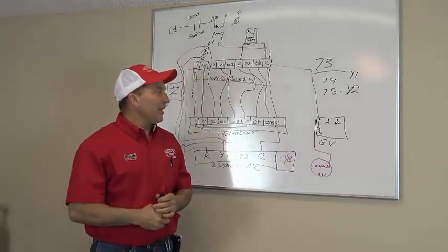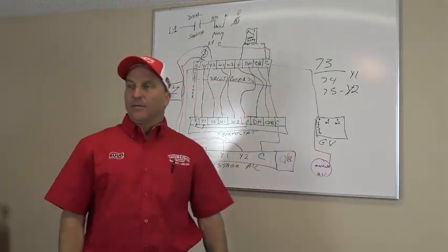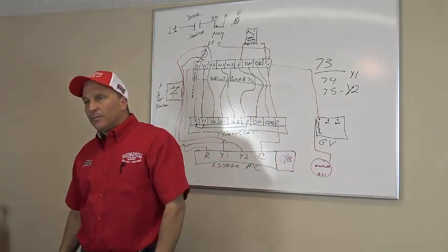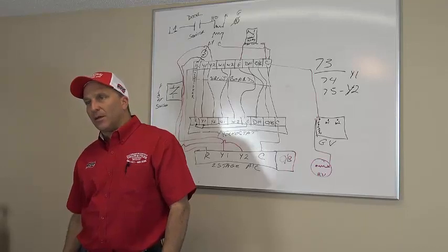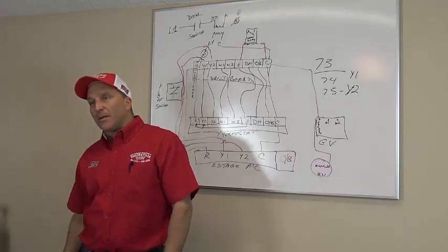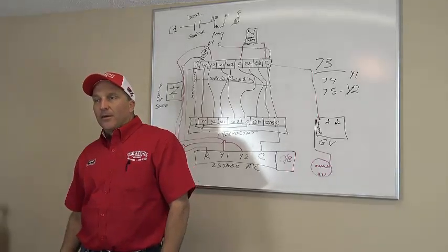Alright? Now, how else will Y2 kick in? Will Y2 kick in if I just go bury the thermostat down? Yeah, it will. But will it kick in right away? No, because there's a little time delay in between. Sometimes you've got to wait 5 minutes. Here's another kicker.